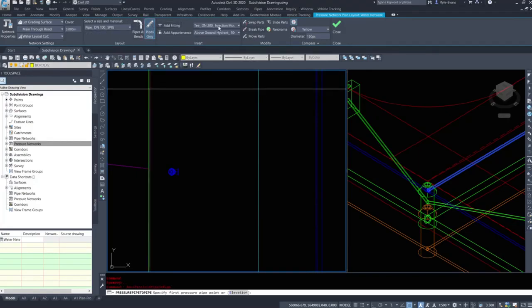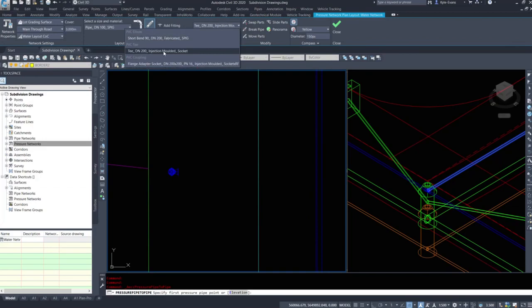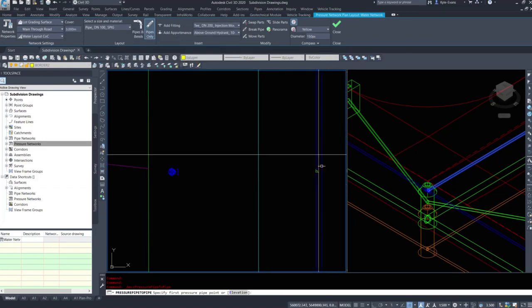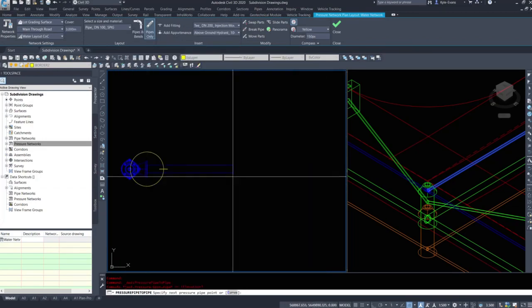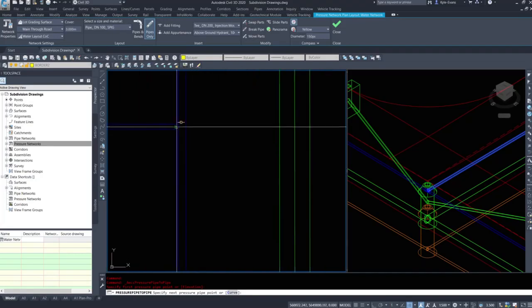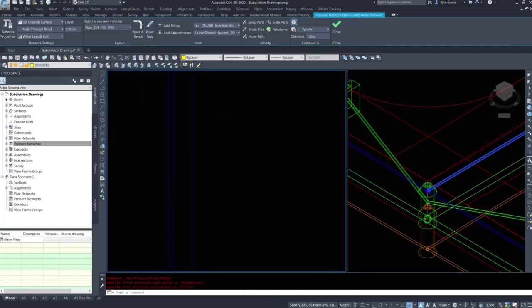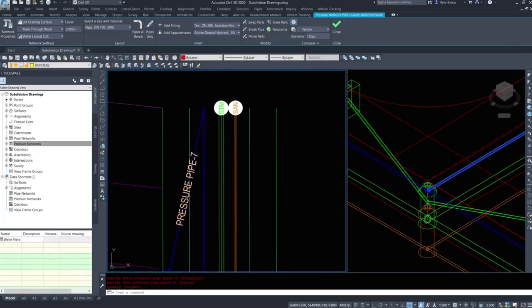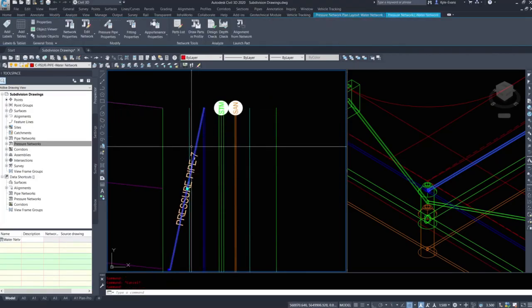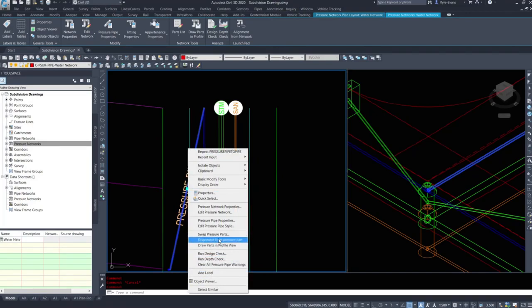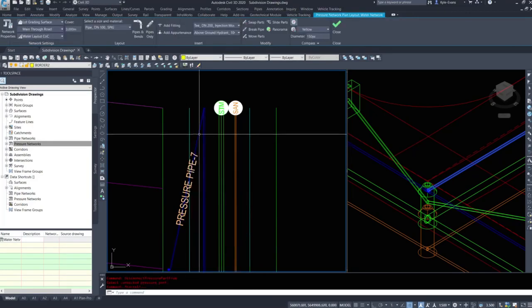So I want to draw pipes only. And then this is where you'll need the additional T that's 200 by 200 by 100 to connect into your water line. So I'm going to just come in here and break this. And it snapped to the end because it wants to close it. I want to disconnect from this part so I can modify it.